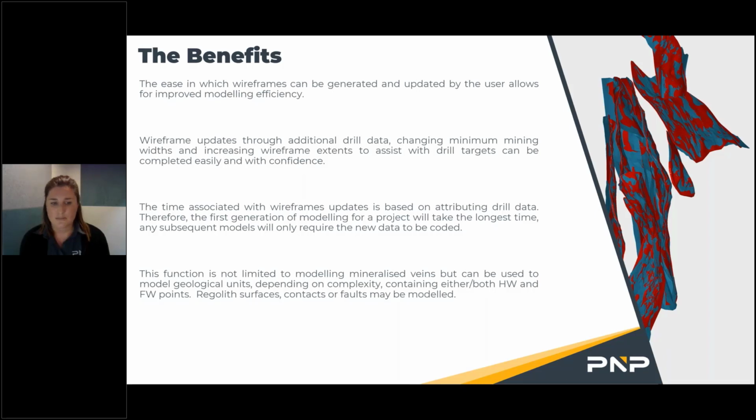And this function is not limited to modelling mineralised veins, but we can use this to model geology units, depending on the complexity. There's still some work going in to the categorical modelling, I believe, which may help with things like granites. But in terms of geology that may be somewhat linear and have a hanging wall and footwall, like regolith surfaces, contacts or faults, you can model these with ease, I believe. And I think the limitation is really on the user and the understanding of the deposit, and being able to code your drill data properly and making sure you've got quality data.